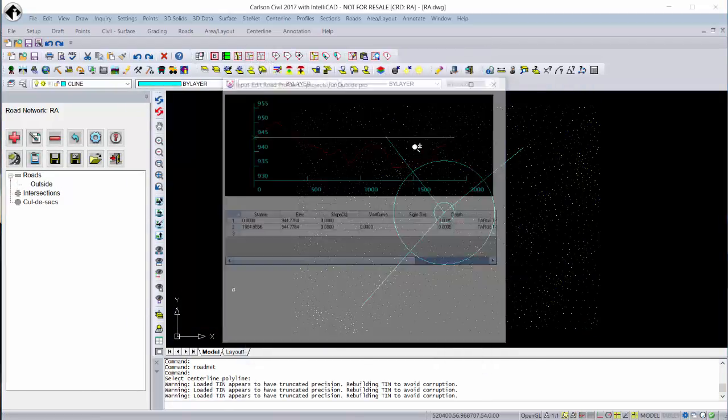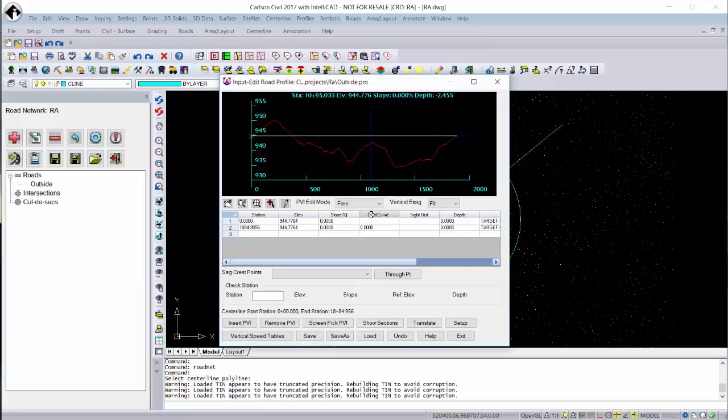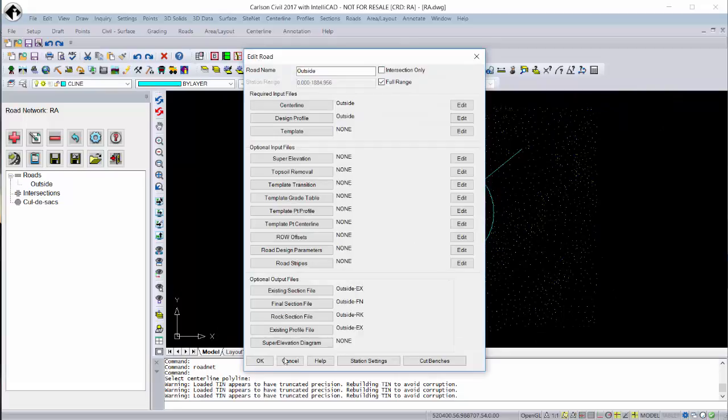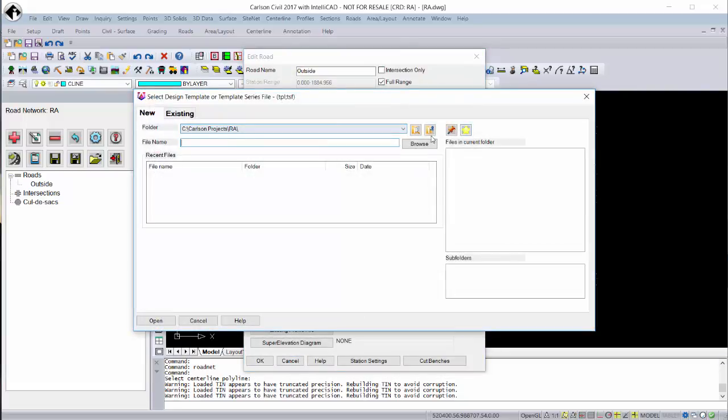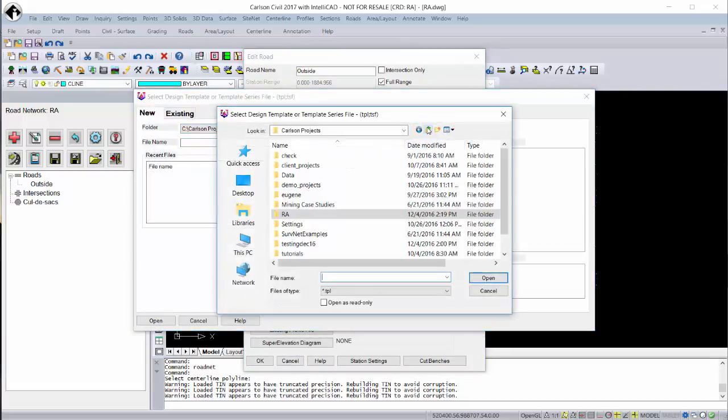Just goes a straight line end to end on the existing ground, and we're not going to be changing the profiles for these. I just want to show you what happens. So we're not going to spend a lot of time fine-tuning the profiles, although you could. And on the circles, what you would just want to make sure you do is come in and out of them at the same grade, so you don't get a sharp bend in them.